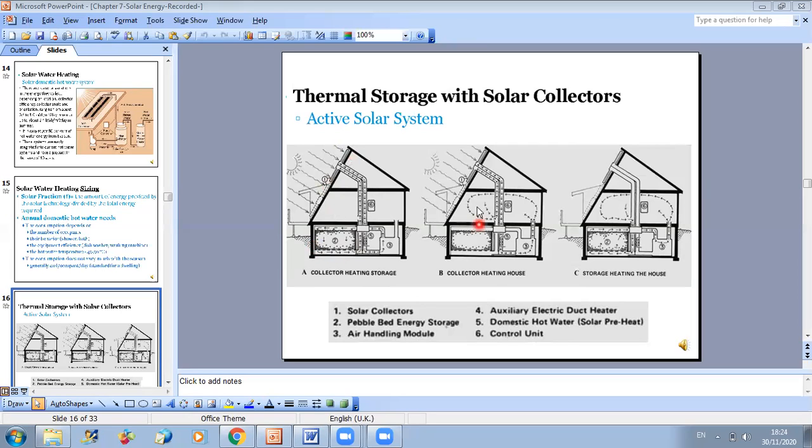Now, once the solar energy is needed inside the space, once the temperature inside my space begins to decrease, then instead of giving the energy to the thermal storage, I can directly distribute the energy collected from the sun to my space. By opening certain vents, I can circulate the fluid along another path.